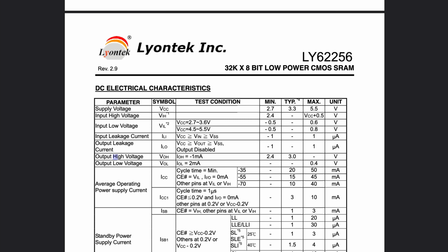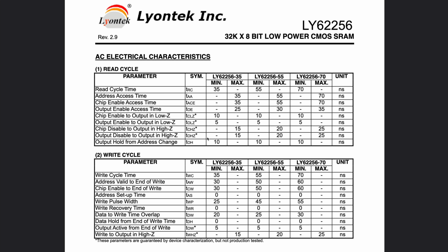If you look at the voltages, you can see that it's also a TTL level chip, just like the ROM. So we're good on that front. And then the timings are going to be much better. The specific chip I'm going to use is the 55 nanoseconds version. It's going to have a total read cycle time and write cycle time of 55 nanoseconds, which you can compare to the 150 nanoseconds of a ROM chip. So this one is going to be almost 3 times as fast. And we'll take a look at the timings in detail later in the video.